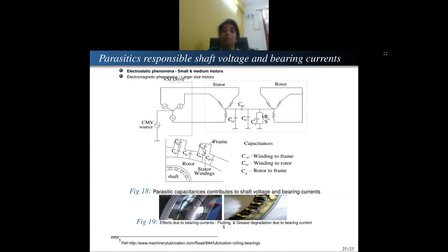If you remember, the purpose of the bearing in the motor is just to separate your stator and rotor. The entire weight is placed on this bearing, right? It separates it. So if the bearing fails, it will lead to complete shutting down of the motor. This is more widely researched on the mechanical aspects, but even the electrical drives give a problem to the life of the bearing.